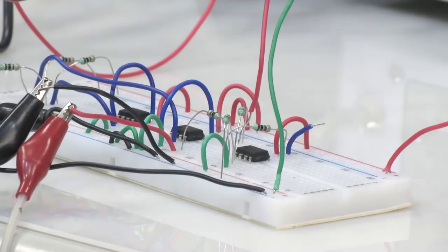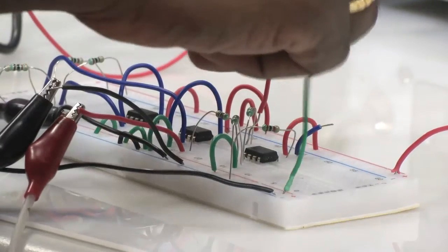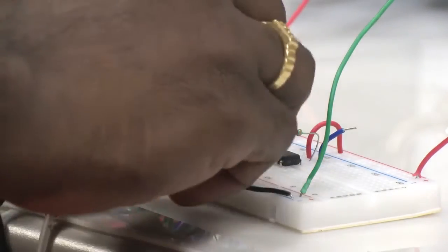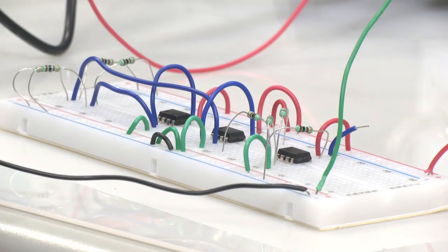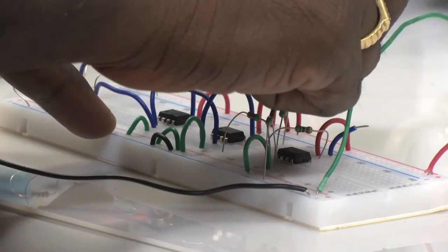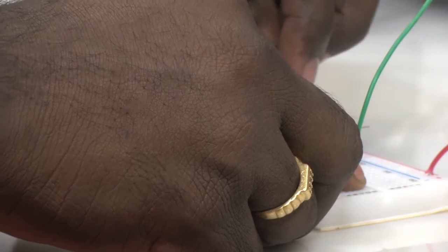Like I said, an instrumentation amplifier is nothing but a buffer connected or integrated with your differential amplifier. So, let us apply the input voltages to the instrumentation amplifier. Now, we have already applied the bias voltage to the operational amplifier, and now we will apply the voltage V1 and voltage V2 to the instrumentation amplifier. Before we apply V1 and V2, we have to adjust this voltage in the function generator.